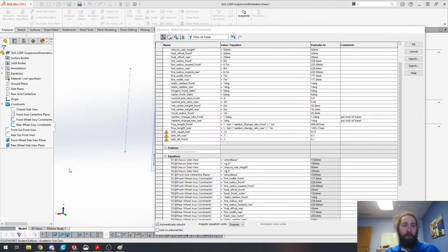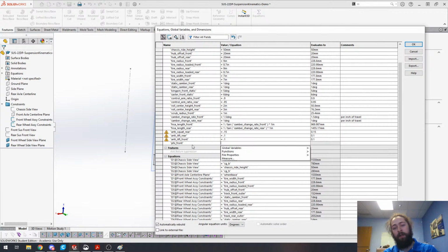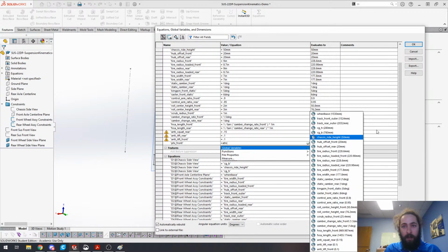To do that, we use those equations that are in RCVD. We back solve for the actual angles themselves, because in their case, what they actually do is they take an existing suspension and they try and calculate what the anti-dive is. In our case, we want the anti-dive to be an input into it, so we back solve. Cool. So we'll define phi in the front, and phi is the angle between the ground contact point, or the ground and the line going to the instant center from the contact point with the ground. Phi is going to be the arc tangent of anti-dive in the front.